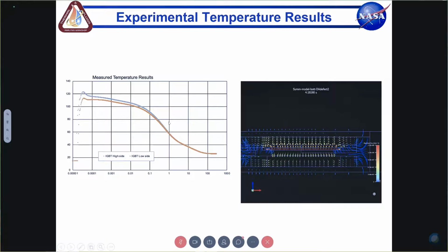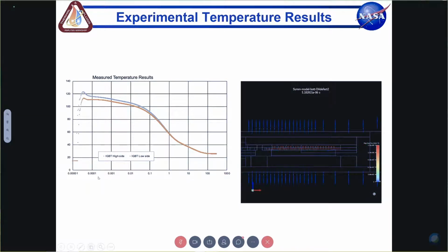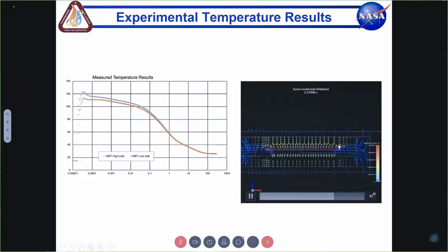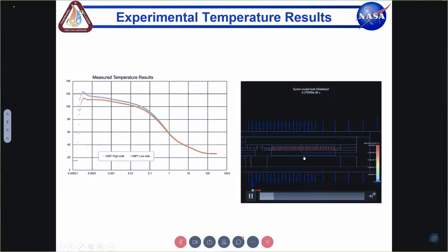In our case, this package had 2 heat flow directions. Even though, as you could see, the structure functions are primarily a one-dimensional model, you can still use it for a 2-dimensional case because their sensitivity to small changes still remains.